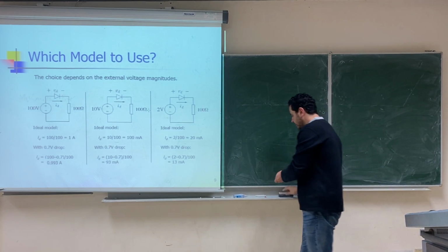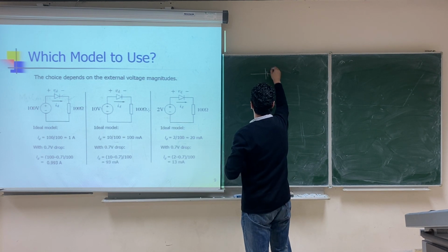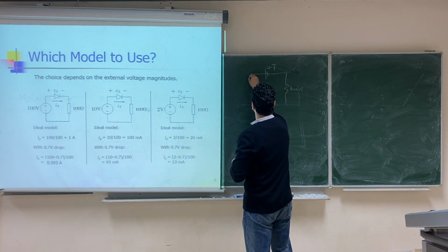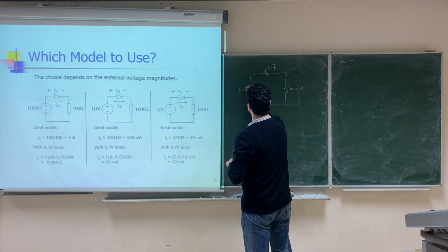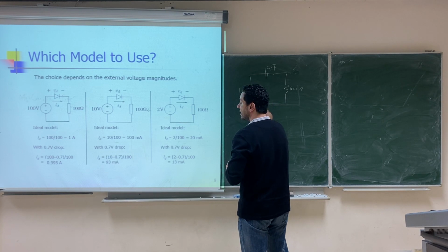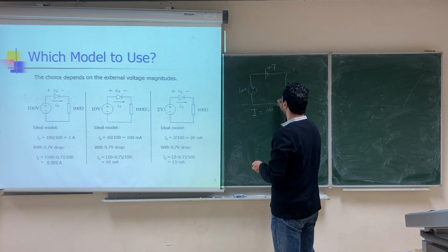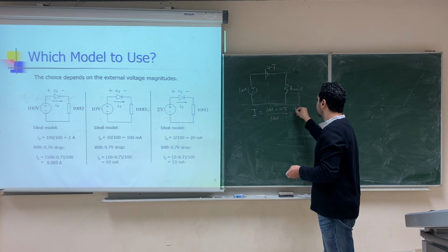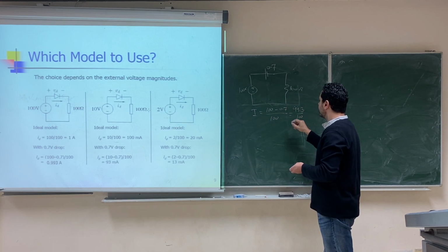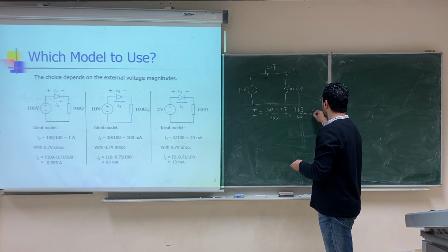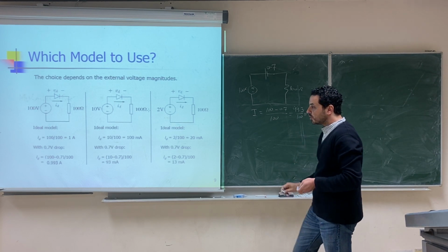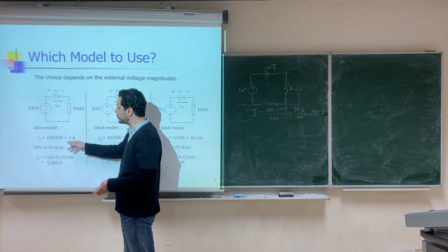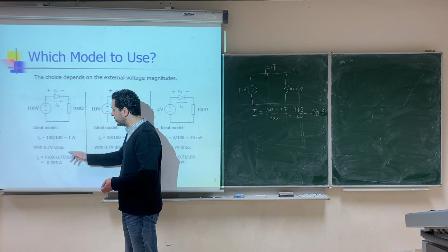When the diode is on, it's going to be represented by a battery of 0.7 volt, let's say. This is the resistance of 100 ohm, and this is our source of 100 volt. Then the current here will be 100 minus the battery of the diode, divided over 100. This is 99.3 over 100, so it will give you 0.993 ampere.